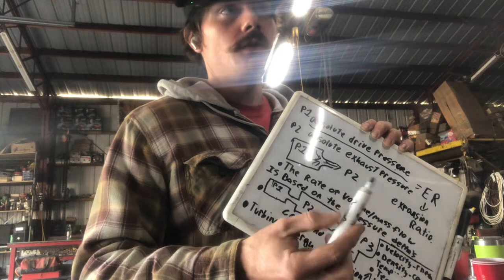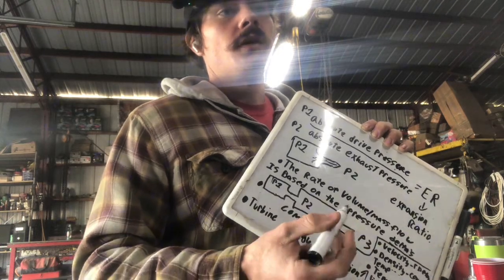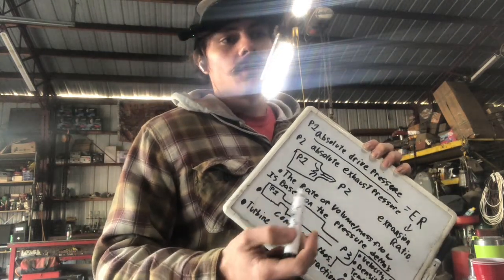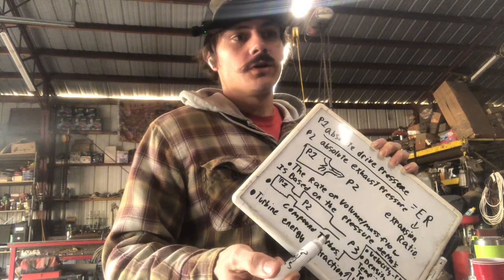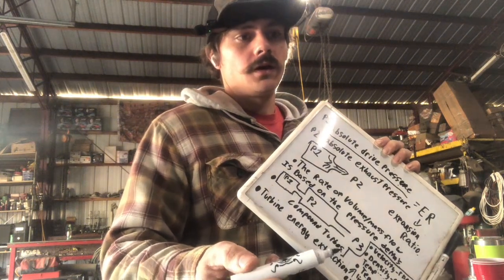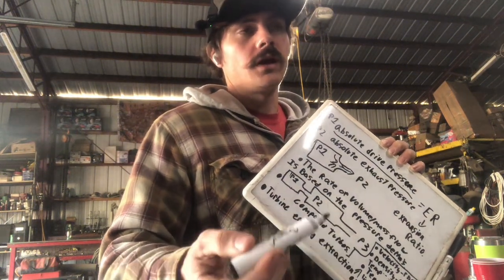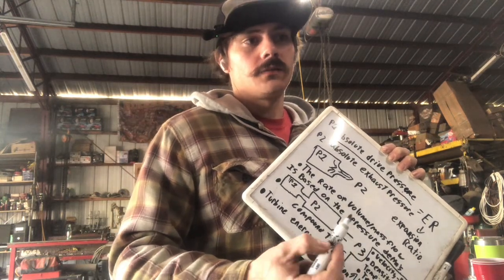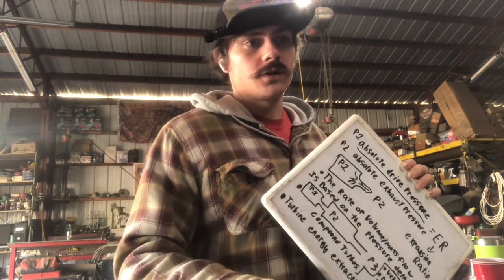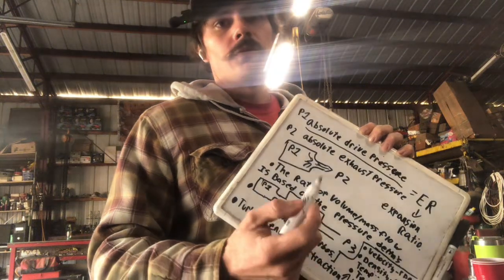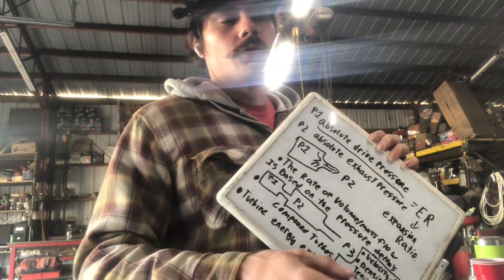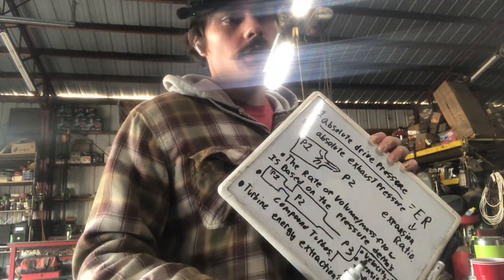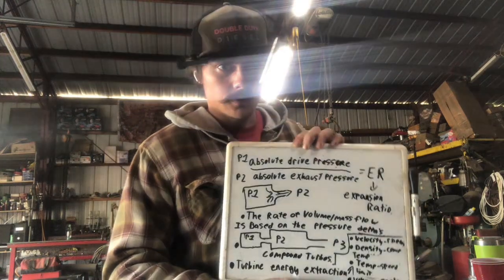They're simulating emissions equipment being on. And you can watch the vane position increase to raise the pressure in the turbine housing to maintain the same exhaust mass flow energy, because you need those pressure deltas across the turbine wheel so it can continue to produce the energy required to meet the boost target the system was asking for.